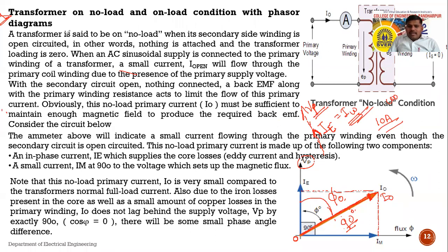So if I write the equation, the no load current taken from the supply, that is I0, is equal to the square root of IW square plus I mu square. If we do not take the square root, then I0 square is equal to IW square plus I mu square. Okay, so this is the no load component, and I0 is the vector sum.